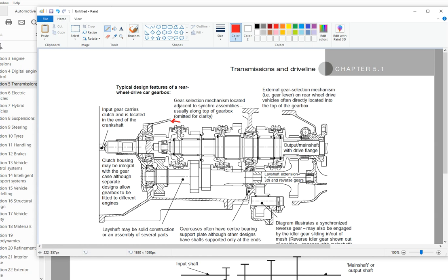is locked together with the output shaft. So in this case I have only a pair of gears meshing, and that's at the final drive, at the differential. Okay, so there'll be just two gears meshing under load. There are other gears that mesh but not under load, so the efficiency is the highest in the direct drive.